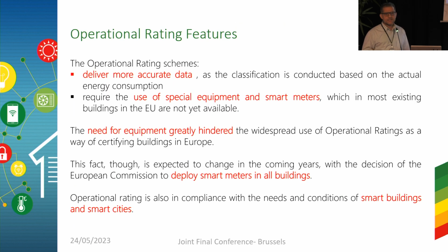If we could discuss some features for the operational rating, we know for sure that the operational rating delivers much more accurate results. It's better to measure energy consumption rather than doing the calculation of it. And apparently when we measure for defining the performance of the building, the results that we have are much more accurate. And this is the one element that characterizes operational rating.